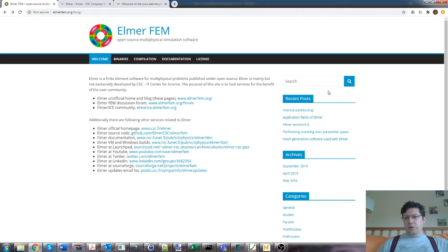The trouble with the compilation comes if your distribution requires Qt5. Elmer is still, I think, on Qt4, and if you build it with the Qt from your distribution, then you will end up with link problems. So you need to get a copy of Qt4 and build it against that. So there's quite a bit of fiddling to do. Well, not quite a bit, some. I managed it, so it's not that hard. I'm a bear, for God's sake.